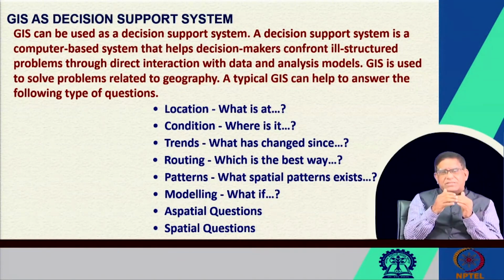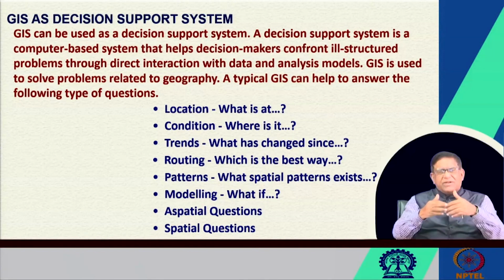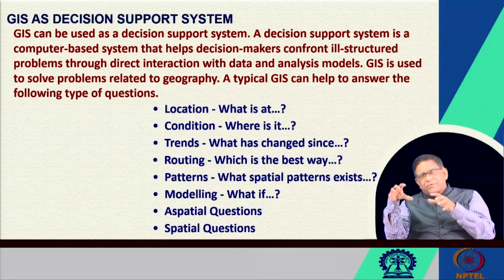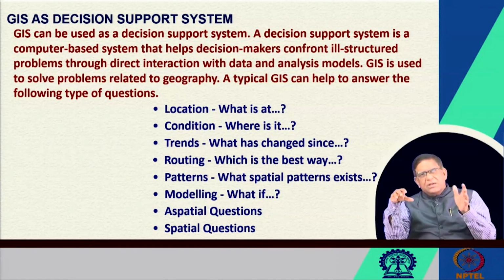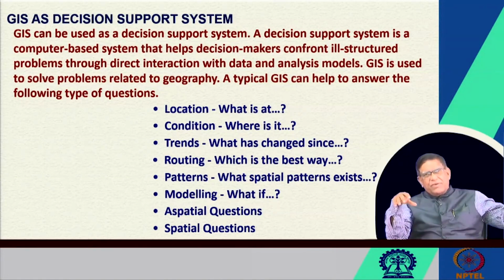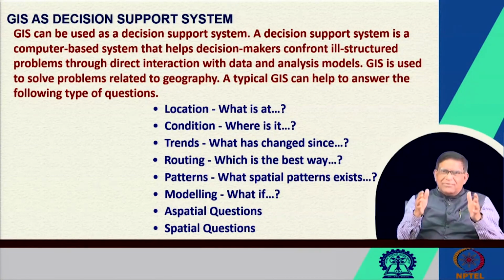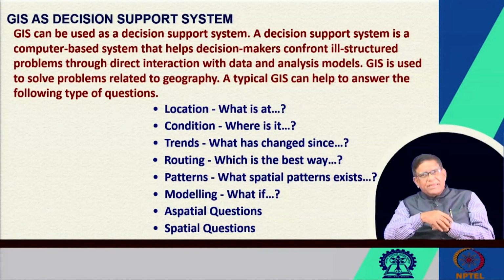If the river is deeper here, you know that sometimes because of floods, bank erosion takes place and the river moves; that is called river migration. Now, if you take the geographic information system every 3 years or 5 years from the past until now, you can put all the data in one table and find out the trend of shifting of the river.